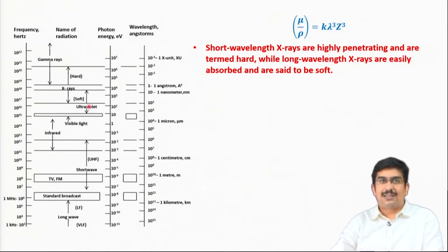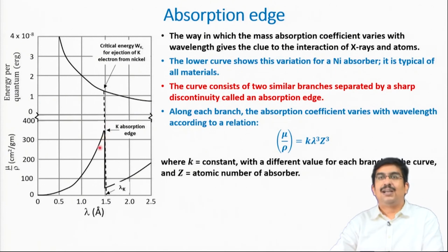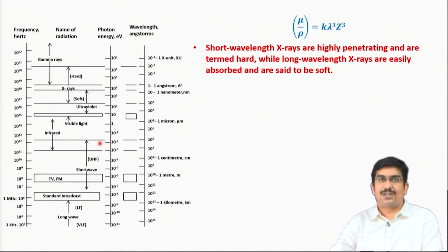So, these X-rays are having higher energy and their mass absorption coefficient is much higher. So, they can be absorbed more and they can produce this kind of contrast or radiographic images, whereas the hard X-rays have a shorter wavelength, the energy is correspondingly higher, and those hard X-rays are having less absorption, which is better for any kind of characterization like X-ray diffraction.